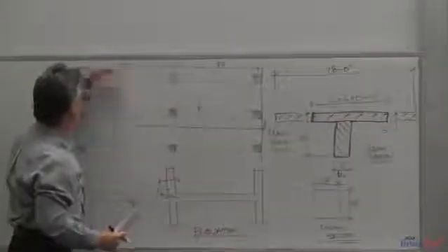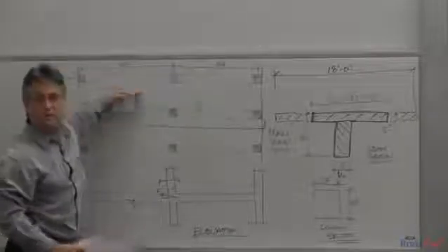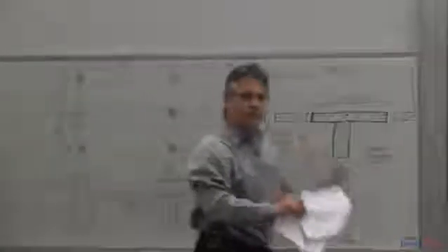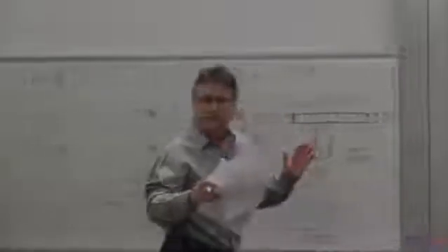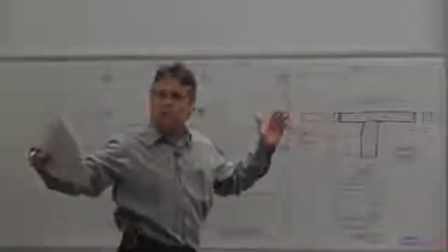Now, I will get people confused, and they're only going to calculate the dead load over 95 inches. And I will ask them, well, what is going to support all the rest of the distance to the halfway point? So the difference between section property width and full tributary width of load that you have to support. Okay, back to it.